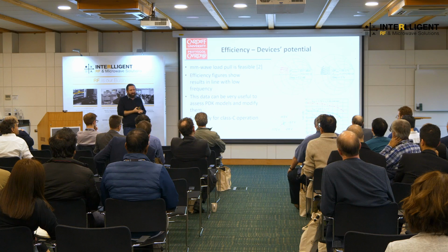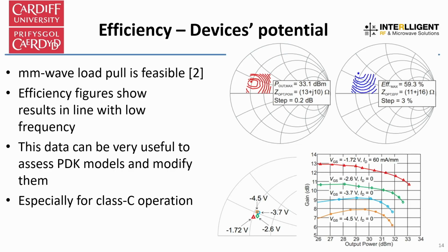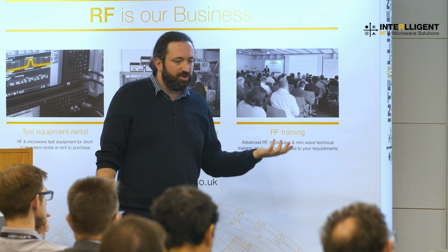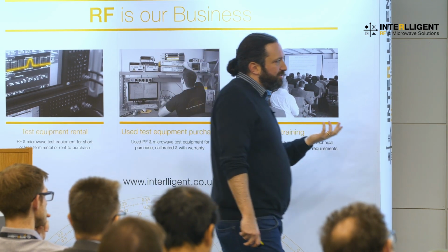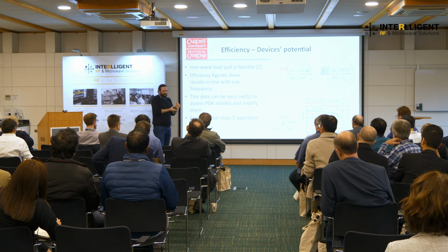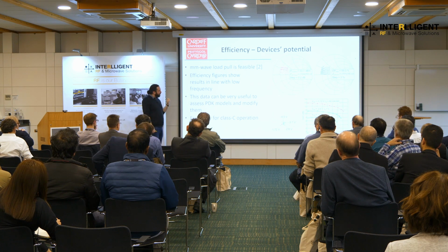Well, first of all, we have the devices, right? So you need to start from a good device to get some good performance. And the first question that always comes up is, can a millimeter wave device have the same efficiency as a device at lower frequency? I think the deep answer is probably related to the slew rate of your device. I don't think it's related to FT, it's more related to the slew rate of the device.